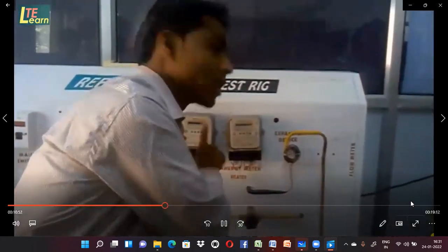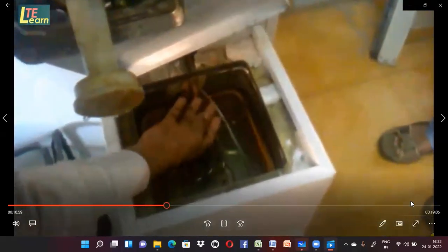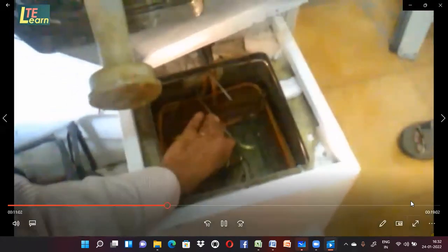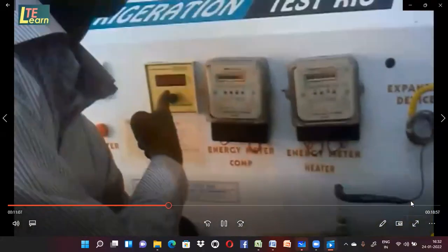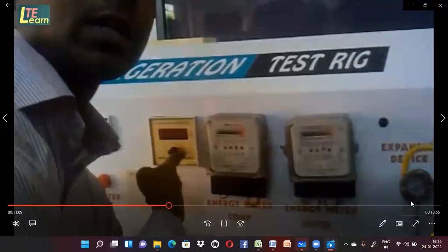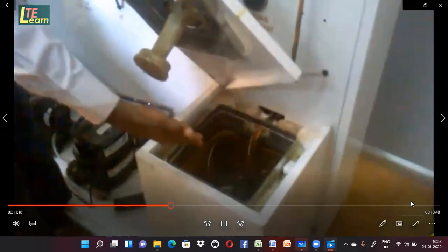And compressor work we can measure by using electrical, this energy meter. So in this, these are three wire-like, these are what? Thermocouple. Now these two thermocouples are connected. One thermocouple goes to this, where there is a display, temperature display. It will give us temperature of calorimeter. That calorimeter means which calorimeter? Water calorimeter. Okay.